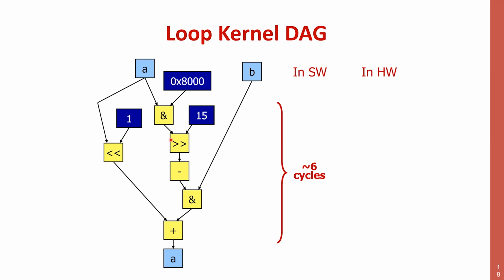Whatever was bit 16, I connect to bit 1, bit 17 to bit 2, and so on, right? So as soon as I'm shifting by a constant, there is no real shifting involved, but a different connectivity between input and output. Okay? So this is again something that contains 0 transistors and that takes 0 time at the first level of analysis. It's just a wire. Okay, last one, and then I'll not do poses anymore, at least not for some time.